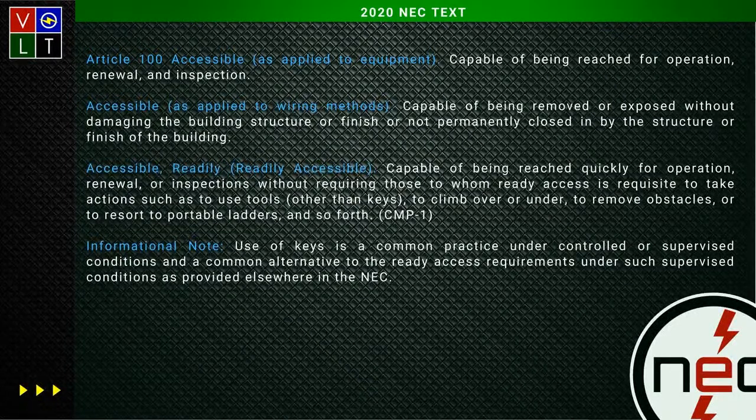The myth is that you don't need GFCI protection for a water fountain, and that is false. The myth is busted. You do need to have GFCI protection for that water cooler. Now, I don't care how you do it. I don't care if you put a receptacle inside the water cooler and then put it on a GFCI breaker. Usually what I do is I just mount a GFCI right below the water cooler and then run the cord out and plug it in.